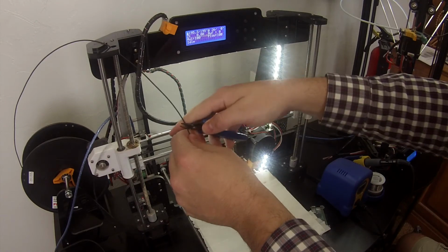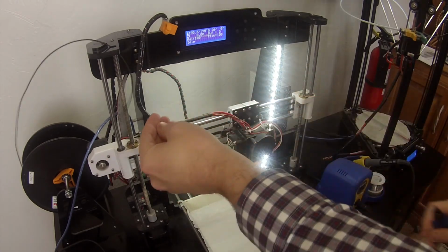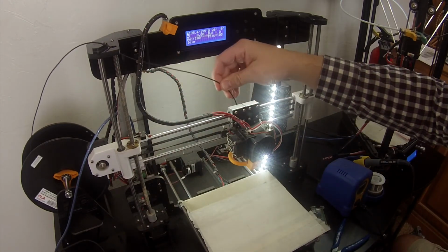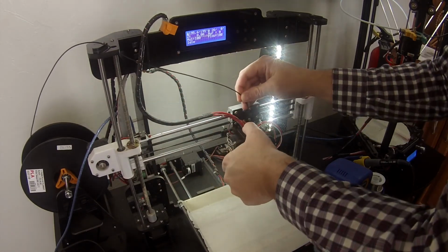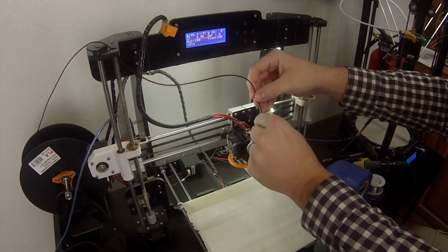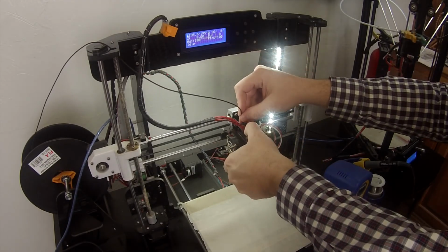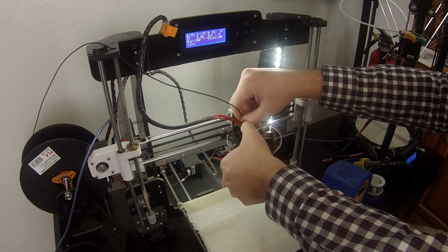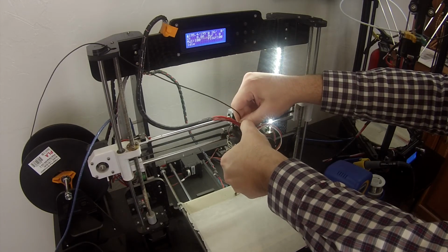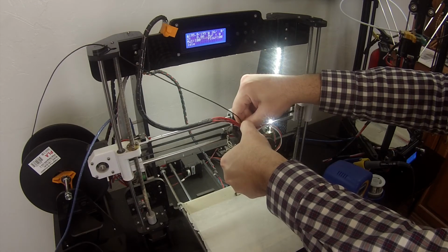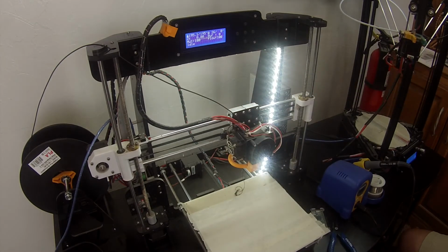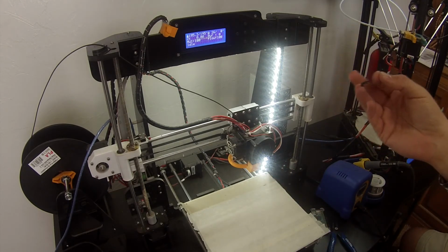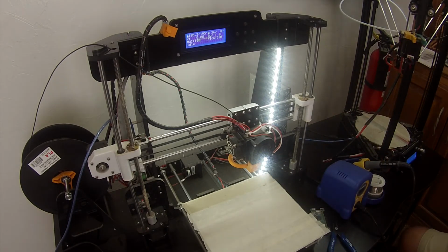And by cutting this at an angle with some of those flush cutters, you make it pointed and much easier to thread into the proper location. Without doing that, it's much more challenging. This one may prove to be a bit of an obstacle anyway. Finally, okay. So you see, all of a sudden, I got the plastic fed into the proper location, was able to push the previous plastic out, and maybe don't go initially and grab this, but it cools off very quickly. You can see it's already solidified down below its glass transition temperature.